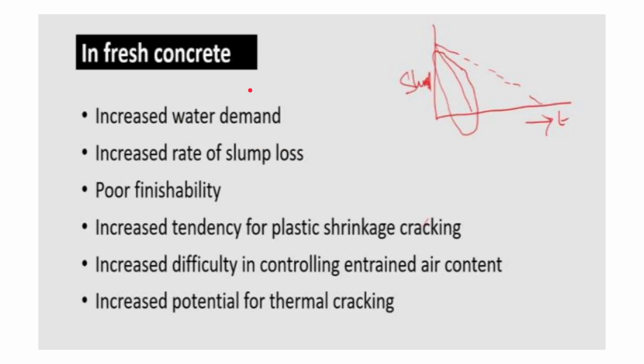In fresh state, due to evaporation, there is increased water demand, because the amount we have added starts to evaporate at a faster rate as compared to ambient, and this results in an increased rate of slump loss. Thirdly, this also results in poor finishability because cracks will develop, and increased tendency for plastic shrinkage cracking as well as thermal cracking potential.